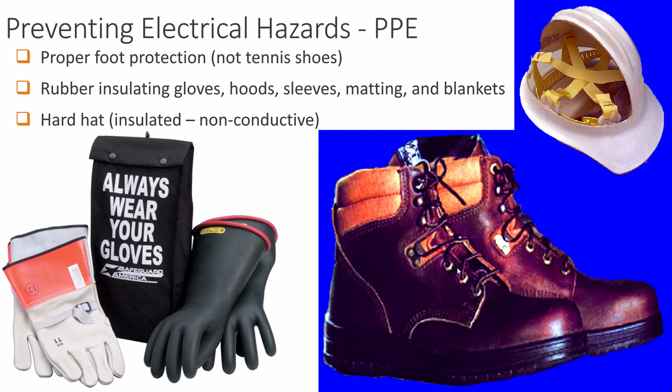You got to test them to make sure there's not any leaks in them, because with any pinhole prick of a leak in that rubber glove, the electricity can find a way, just like lightning can find a way to ground. It can still arc through. And then we protect those rubbery gloves from getting those leaks by wearing a protective thin leather glove over top of them.